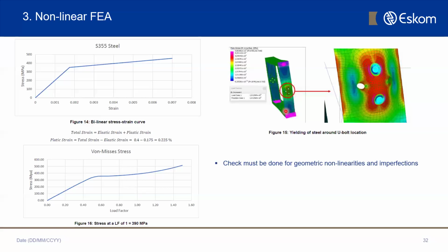If the box section has enough imperfections, and if the box section is too slender, you could have buckling as well. And your buckling coupled with your material nonlinearities could cooperate together to cause failure a lot sooner than expected. So I say this because you then need to at least check if geometric nonlinearities will become a problem. You can do this by performing a linear bifurcation analysis.